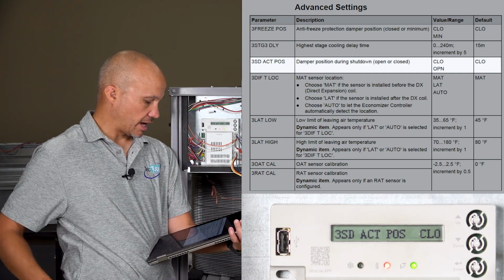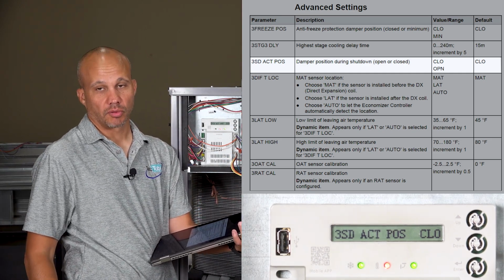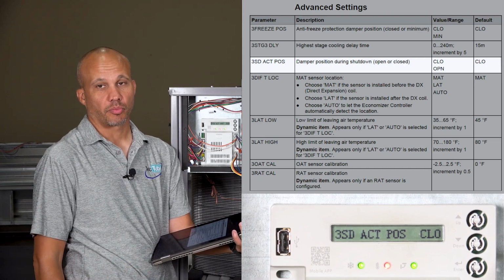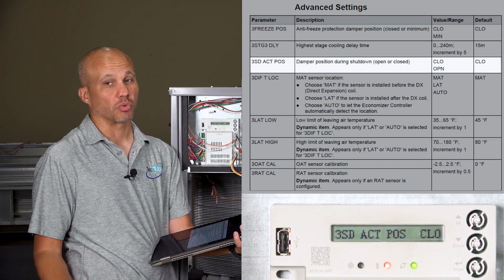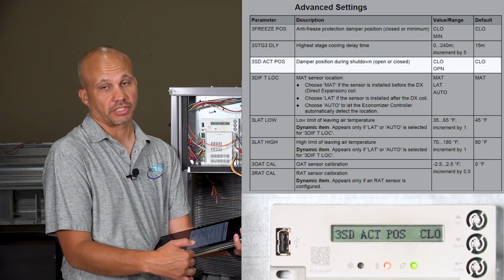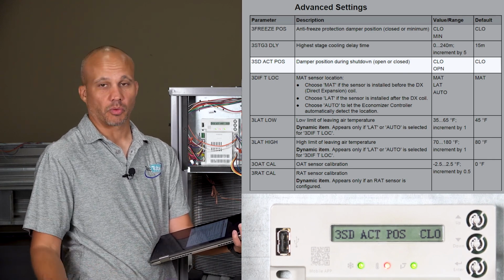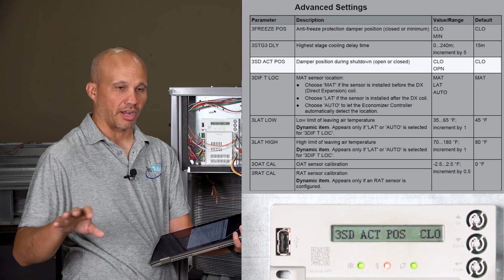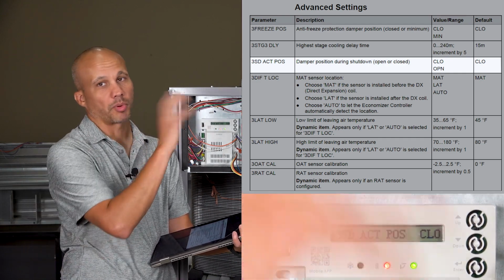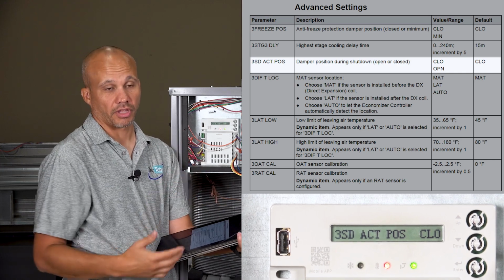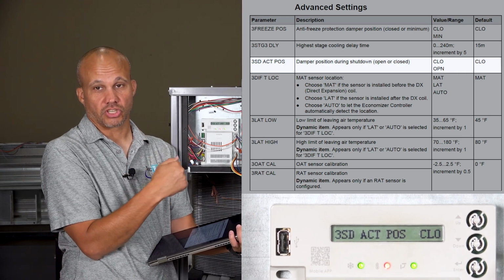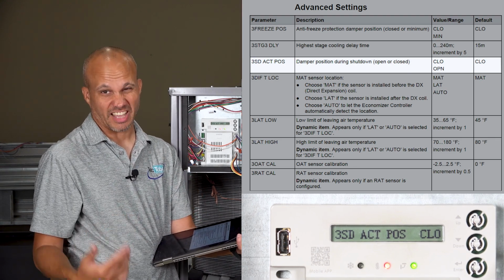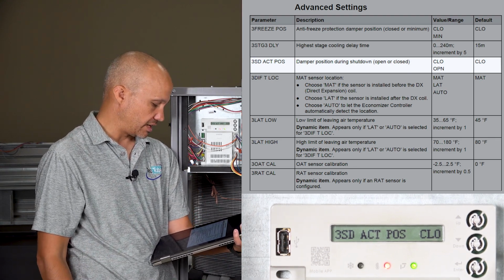Actuator position, closed or open on a shutdown. Normally, when there's a shutdown, you want to close the damper off. That would be normal. If you had a weird project where you wanted to open it, like maybe you weren't using the shutdown input for an actual shutdown, you're using it for something else, some kind of weird manufacturing thing, and they got, hey, when we turn on these exhaust fans because we had a problem with our process, we had to purge a bunch of air, we also want to open up all the fresh air intakes at the same time. Okay, we can do that. We'll wire those into the shutdown input on the controller, but shutdown will really mean open everything wide up. Do the opposite of shutdown. So you can do that if you needed to.